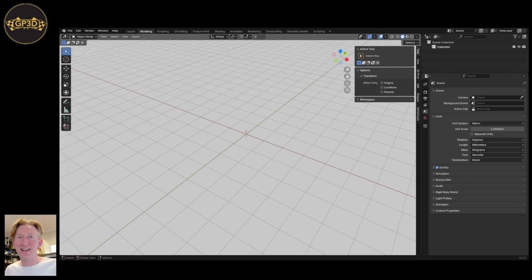Okay, I'm back. I haven't done this for many years now, so I had to do a little bit of Googling and play with it. So the idea here is we have to set the settings I've already showed you, so I'll just pop through those quickly, and then create an object, set the scale and the size we want, save the default, and then come back in, close Blender, come back in, and then we get our default settings saved for all of your future instances from then on.